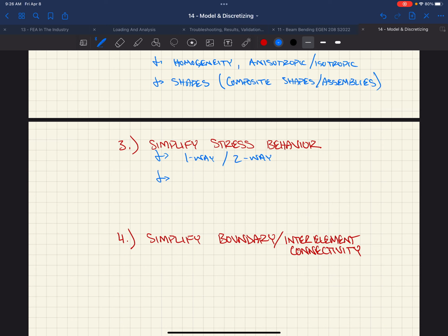That span, obviously it's. But it depends on which way you wanted to assume that it's, right, I mean, if you assume that it spanned this way, you'd have to design it that way, right? You'd have to look at the forces that that concrete would see, and you'd have to make sure that it can handle it going that way. You could go through a table value and say, okay, maybe this is 12 feet, right? And then this is 6 feet,